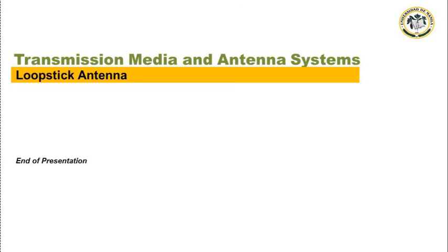Loop antennas consist of a loop of wire that interacts directly with the magnetic field of the radio wave, rather than its electric field, making them relatively insensitive to electrical noise, with about a quarter wavelength of the antenna. The basic configuration is a powdered iron core with a certain permeability. Permeability is symbolized as mu.